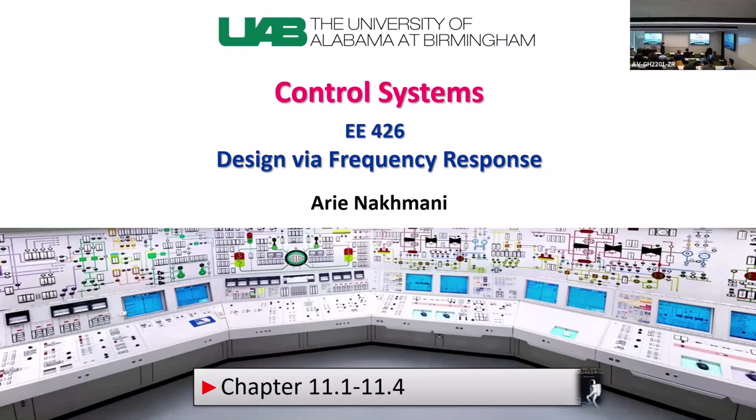Let's move close. All right, so just to remind you what we talked about last Monday, we talked about frequency domain methods for designing controllers, and we discussed how you design just gain controller, which is K, and then we discussed how you design lag controller, and we stopped at lead controller. And lead controller will be very different from lag controller and K design. The intuition behind it also will be very different. And I just want to go through these ideas just to summarize what we learned previous time.